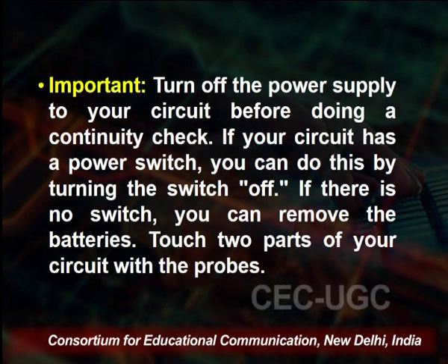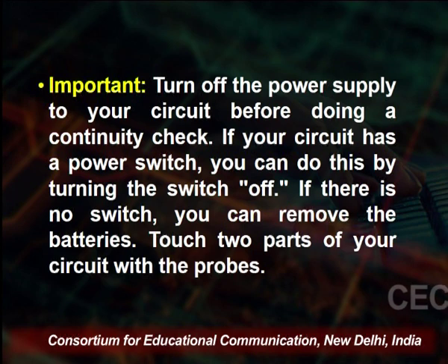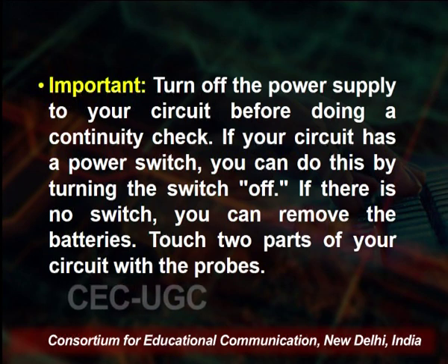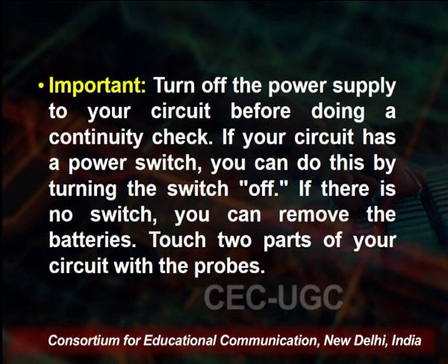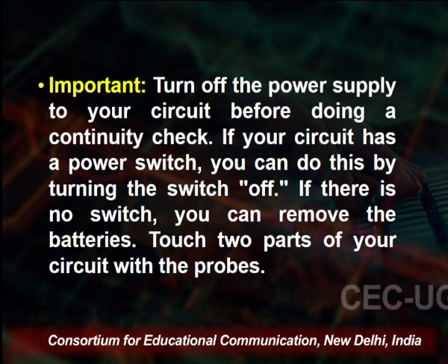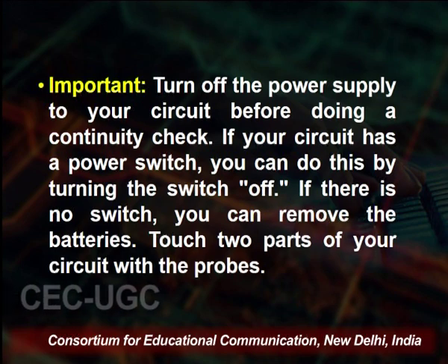If the circuit has a power switch, then we can do this by turning the switch off. If there is no switch, then remove the battery. Again, touch two parts of the circuit with the probes.